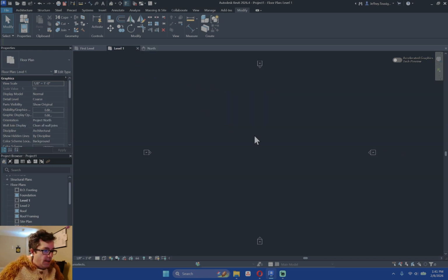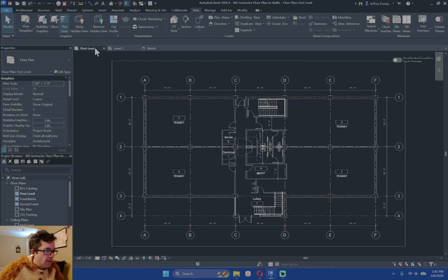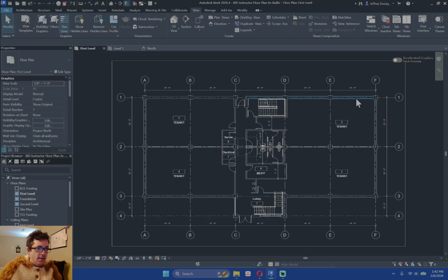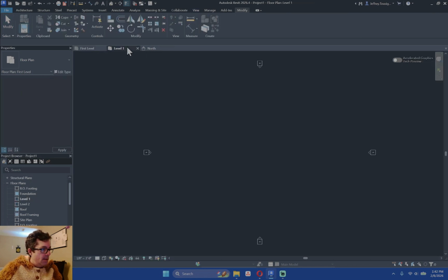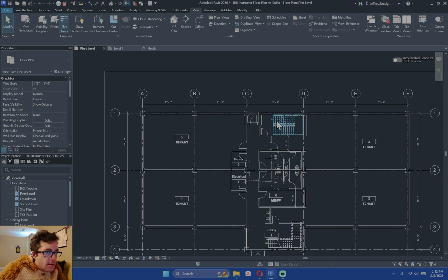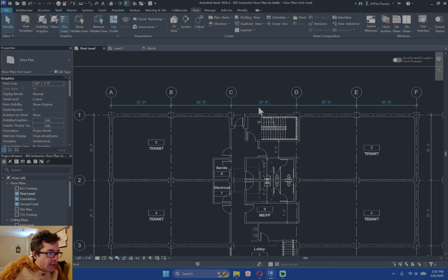So now let's do grids. Our original building had 6 vertical, 4 horizontal, 3 horizontal for the main building, and then the 4th is going to the columns in the front. It also looks like the columns have been designated to go on center line. So let's just go ahead and do that. They're all 23 apart from each other, except for in the center.